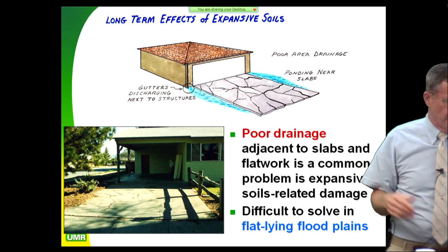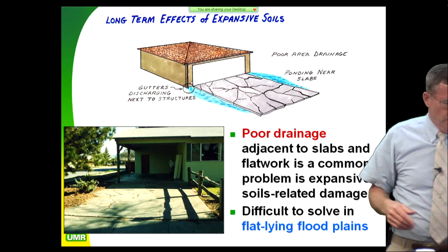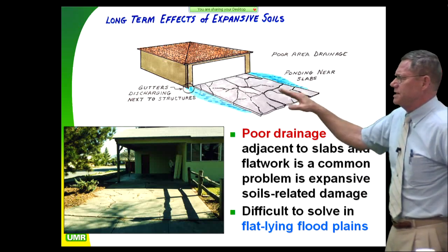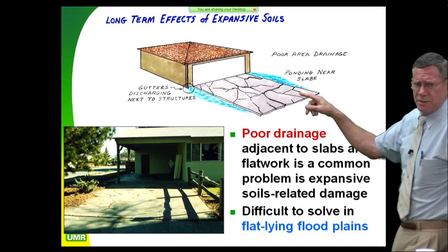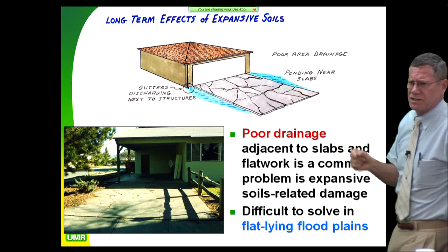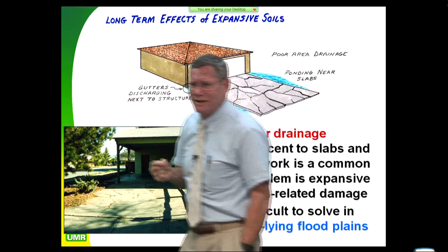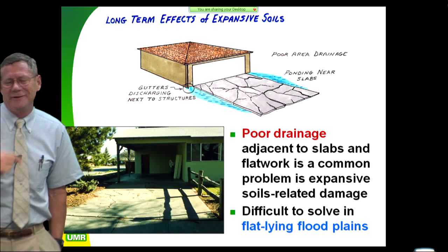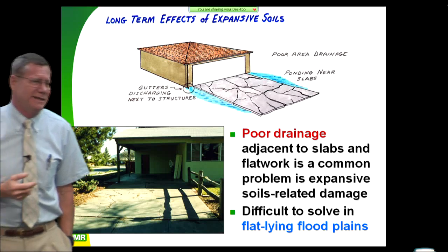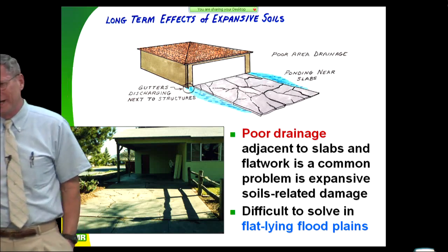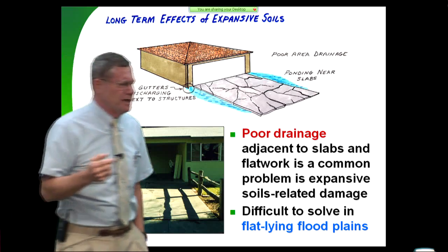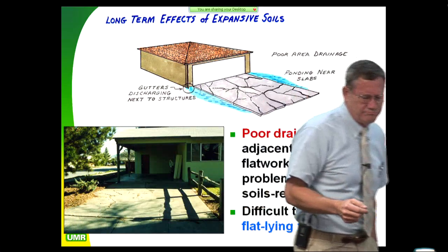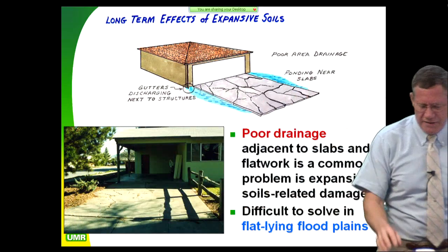And so you're going to have poor drainage. So when I say non-reinforced, that means it doesn't have rebar. They probably have temperature steel in it, which is welded wire mesh. Welded wire mesh, contrary to what a lot of contractors will tell you, is not reinforcement. That's just temperature steel, and it's not worth a whole lot. It's better than having nothing, but not much better than having nothing. It's close to having nothing.